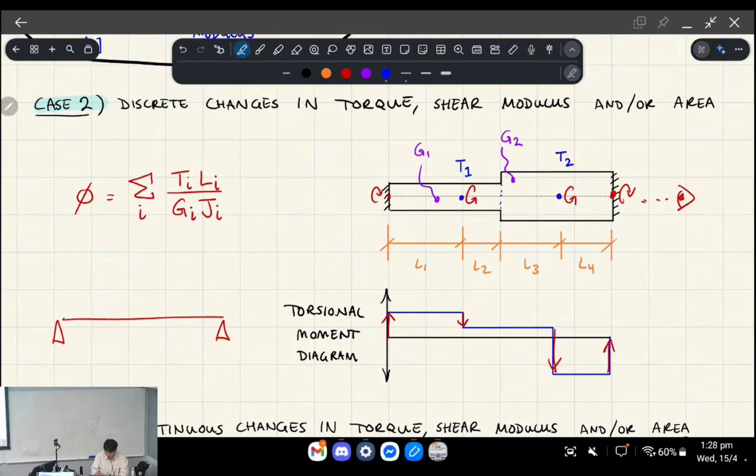So what I mean by that is just imagine you've got a simply supported beam, and instead of point torques, which is how I've drawn it there, if you instead have a clockwise moment on a beam like this, sorry, that one's the same way. So this is going clockwise and this is going counterclockwise, on the beam. A clockwise point moment actually gives you a positive, it makes you jump upwards in the bending moment diagram, if that makes sense.